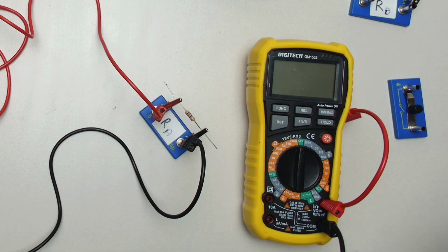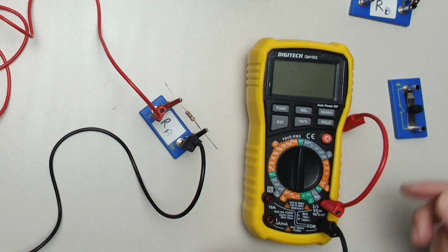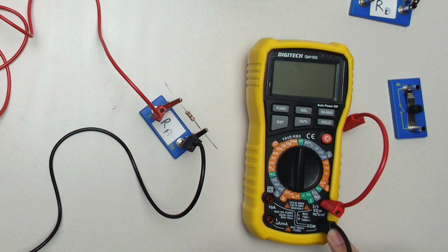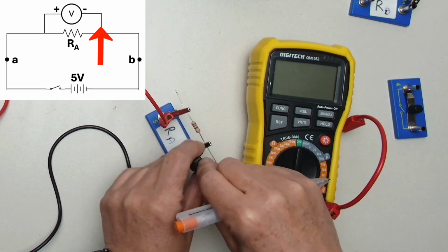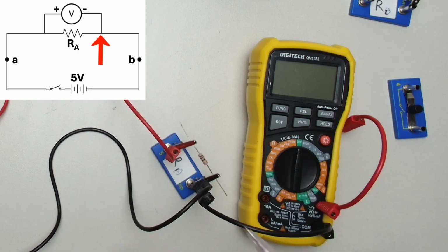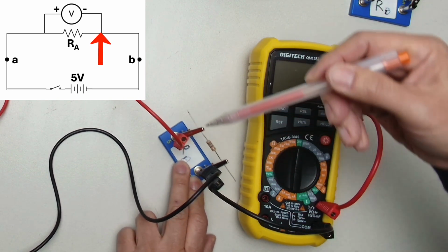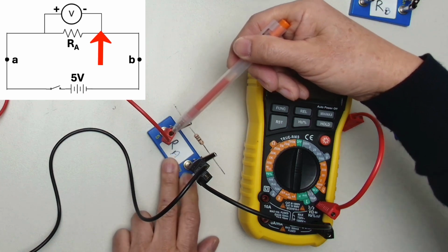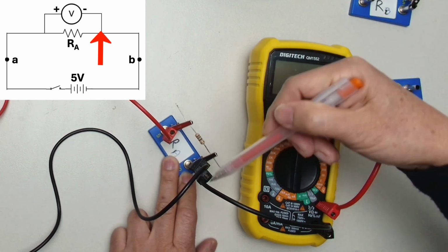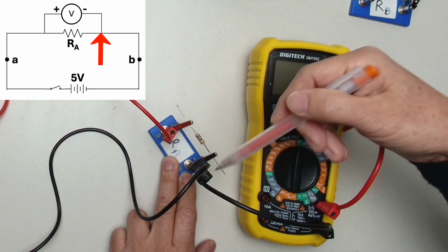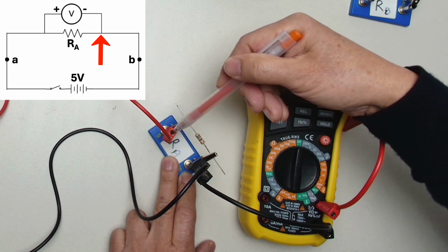Now when we use the multimeter here, we always put the low voltage at the common, because common is like a reference point. It assumes this is the zero. So what I mean is if we put here, we'll expect with respect to this point, it's going to measure the voltage at this point. And we know this is low or zero, in fact, and this should be 5 volts.